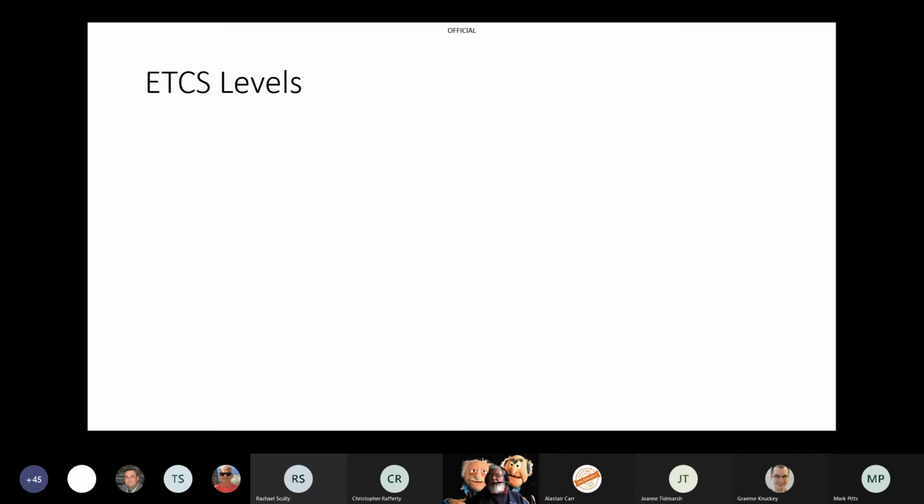I'm sure quite a lot of you know these anyway, but ETCS has got three core levels. Level 1, which is designed for the movement authority to be issued by Balises. There are some options around using Euroloops and radio infill, but principally the movement authority is issued by the Balise in the four-foot, and it is referenced to that Balise.